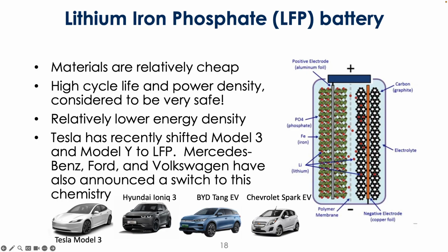But not only that, right? We're balancing economics against these other attributes. These tend to have very high cycle life, very good power density, and are considered to be very safe. And so actually some of those lab experiments that I was showing at the beginning of class, when you do that to these LFPs, they barely degrade.